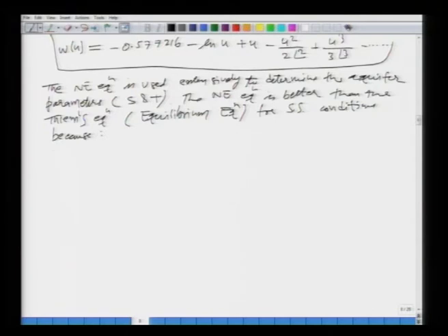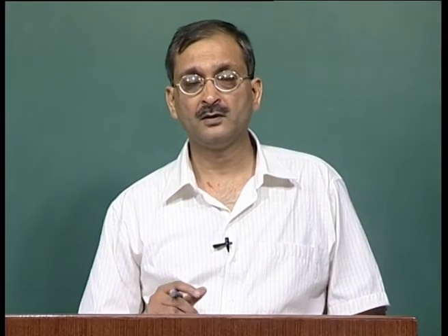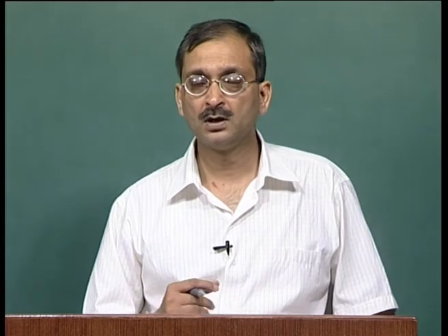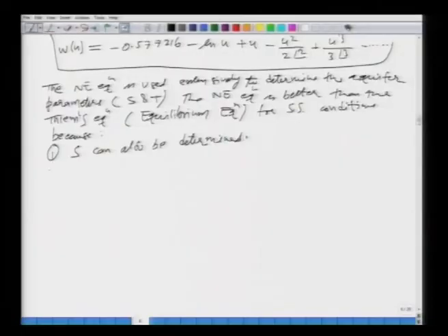Number 1, S can also be determined. You see that if we use the equilibrium equation or the equation for the steady state conditions, we can only determine the transmissibility. However, if we use the non-equilibrium equation, it allows us to determine not only the transmissibility T, but also we can determine the storage constant of the aquifer S.